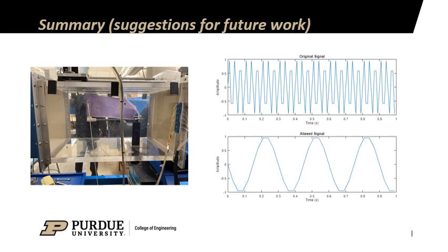Overall, we were able to show the increase in drag force and effective drag coefficient for a flag versus a plate. We were also able to show the positive correlation between the increase in length of a flag and the increase in drag force. However, our results for this relationship with the drag coefficient may be inconclusive due to the small number of available data points at higher speeds, due to the flag being damaged at these speeds. We were also able to characterize the frequency response of the flag for each velocity and flag length and showed a clear positive correlation between the frequency and the lengths.